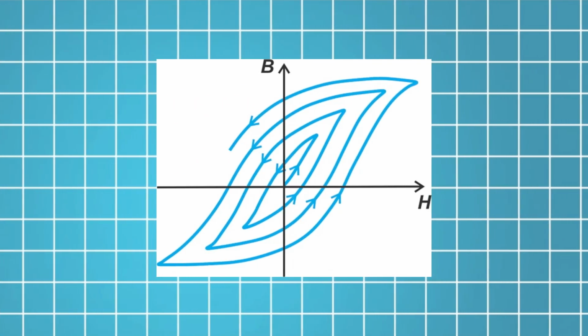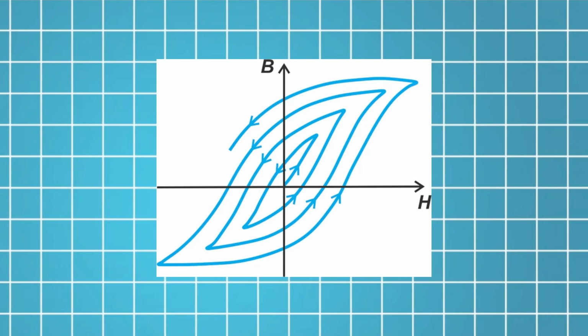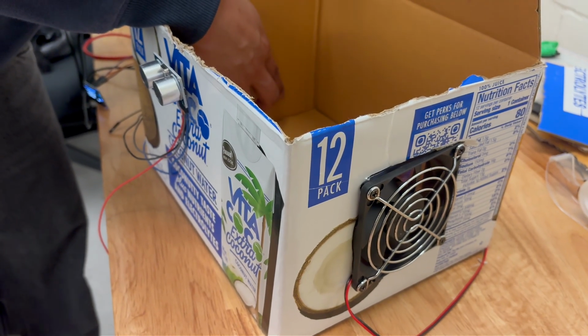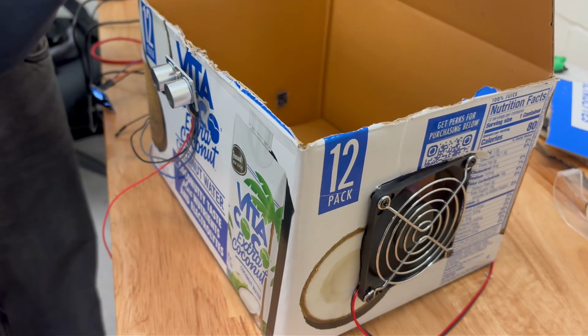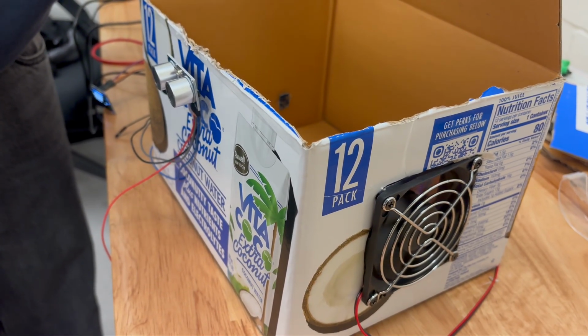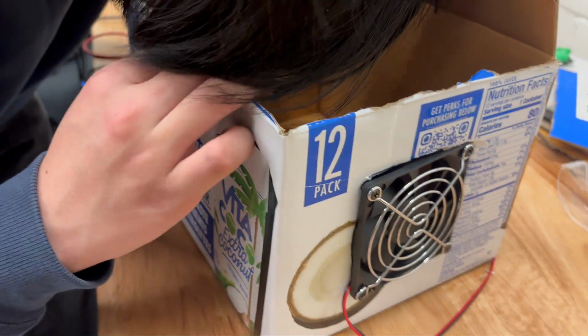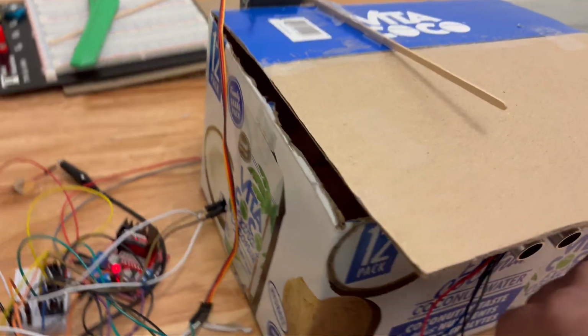For the fan control, we use the hysteresis model where the fan turns on above a set humidity threshold and off below a lower threshold to prevent rapid toggling. For testing trials, we set the difference to 2 units for fast troubleshooting. The lid uses the simple distance-based threshold. When the measured distance from the ultrasonic sensor is less than a defined value, the servo motor is actuated to open the lid. These thresholds act as set points in our feedback control system.